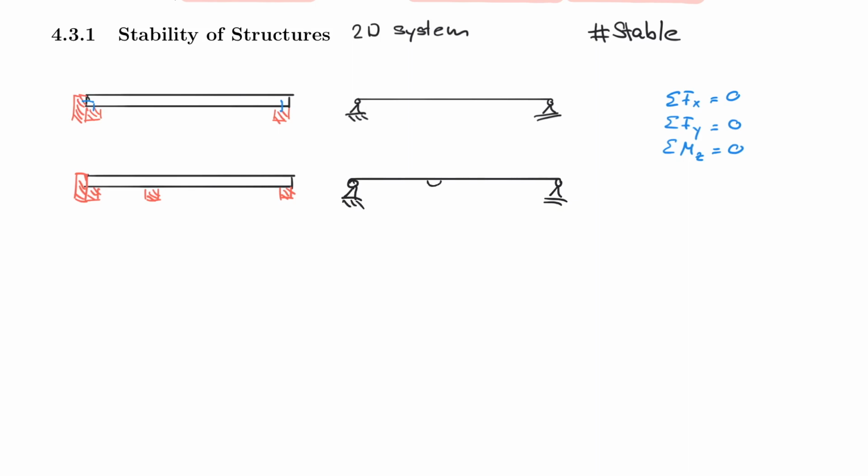And be careful, this support here sits underneath the beam. So it's not a circle through, right? So please understand that this here sits only underneath the beam and not in the beam. That makes a difference, as you will see later throughout the lecture. But now we can still fulfill these conditions, but we have one support reaction more. And as you will see in a little bit, you can actually not solve this system with the methods that we have. And maybe you can already guess why that is.